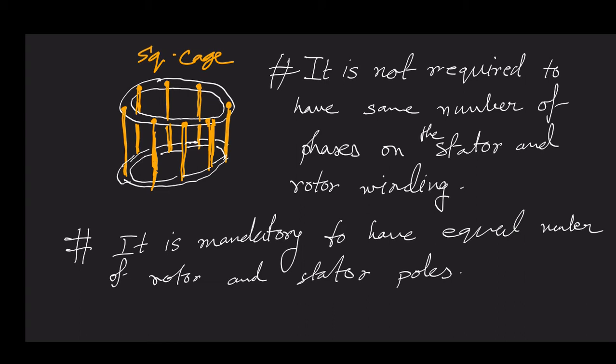Now, if that is the case, then for all the machines that have variation in reluctance path, the flux lines will always find a minimum reluctance path, and whenever they feel a compulsion to pass through a path that is not of minimum length, they will try to bend that path in such a way that they can avail minimum reluctance path, and by doing so they produce torque.